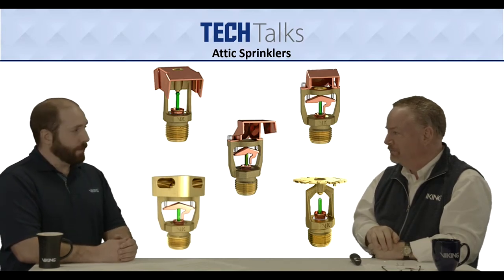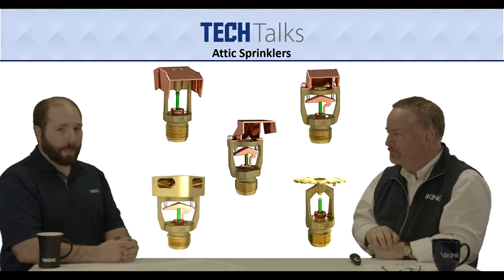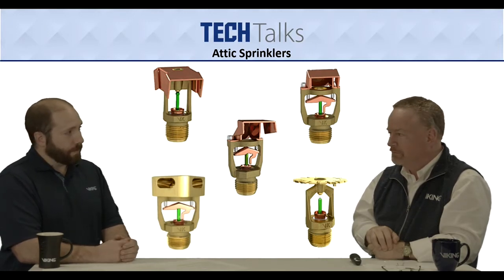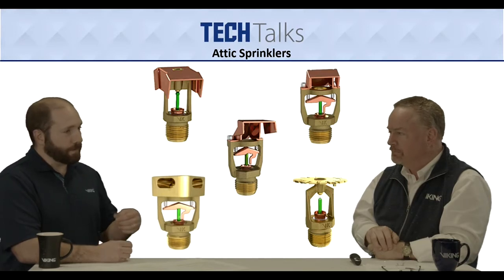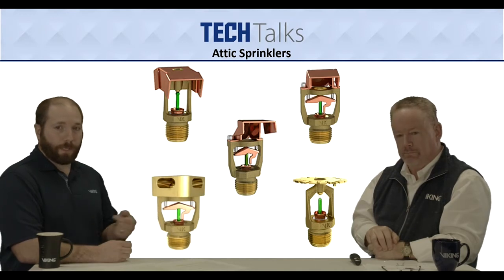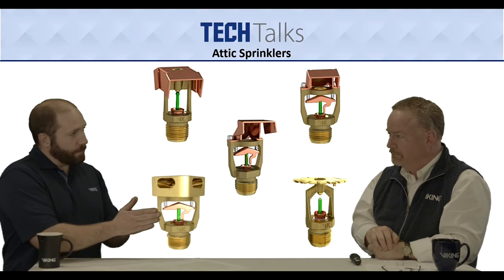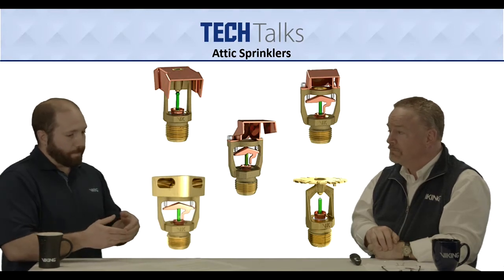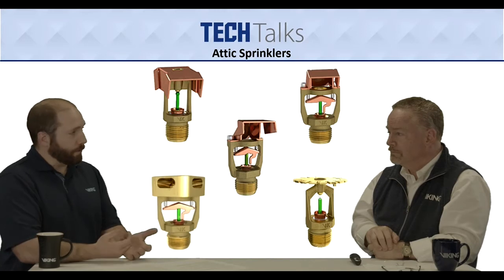In the center there, we have the BEP sprinkler, so eave protection. It's actually a downslope sprinkler, which is pretty unique. It's a completely different design than using the back-to-backs or single directionals or our hip sprinkler in combination with the attic upright. The BEP can use the attic upright and cover wider spans, but also help reduce flows for low pitch attics.